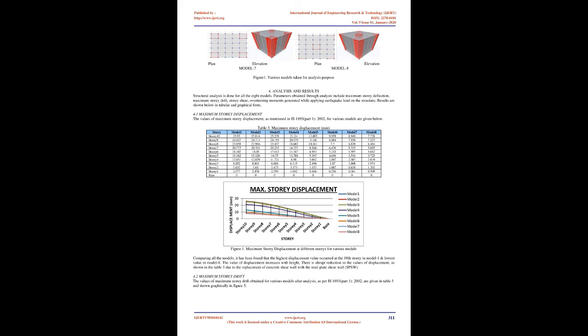7. Drawing the wall of the building. Quick draw wall properties of wall section. Select wall properties, draw the wall. 8. Designing the shear wall. Wall of the building assigned shell pier label, choose P1. Apply. Select wall of building assigned shell spandrel label, choose S1. Select wall of building assigned shell wall auto mesh option, advanced modify, auto mesh rectangular. Select wall of building assigning the load.